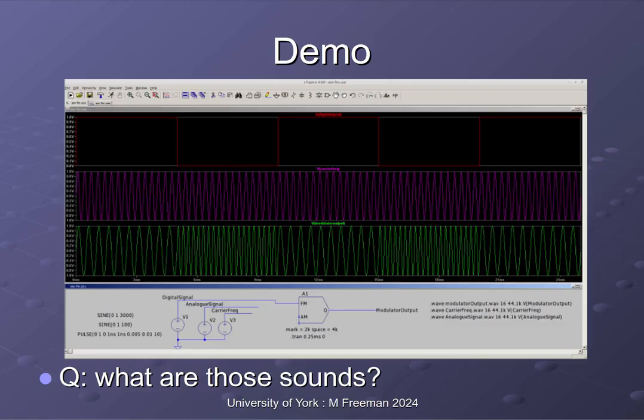To have a look at these concepts in a little bit more detail, we can simulate these analog signals using SPICE. Oh, goodness me, simulation program with integrated circuit emphasis, I think, from my memory, but basically an analog simulator. So we can look at what happens to a digital signal if you were to transmit it down a transmission line, so you see the attenuation, and we can look at some simple frequency shift keying encoding, so how we represent our ones and zeros as tones. We'll have a look at that in the review lecture, so we'll see how we can use SPICE.